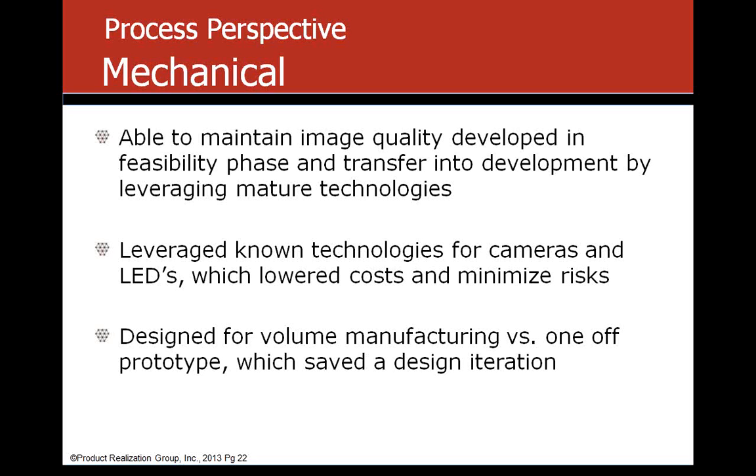And I think the last key point in our point of view was one where we designed the system for high-volume manufacturing, in this case mostly plastic injection molding from a mechanical point of view. There are some other soft components as well that were designed for long-term manufacturing. The whole point here is to design for the end game so you don't have an extra design iteration. On many programs, there's a prototype design that's not manufacturable in volume, and then you redo that for a volume solution. And we went straight to the volume solution, saving an iteration.